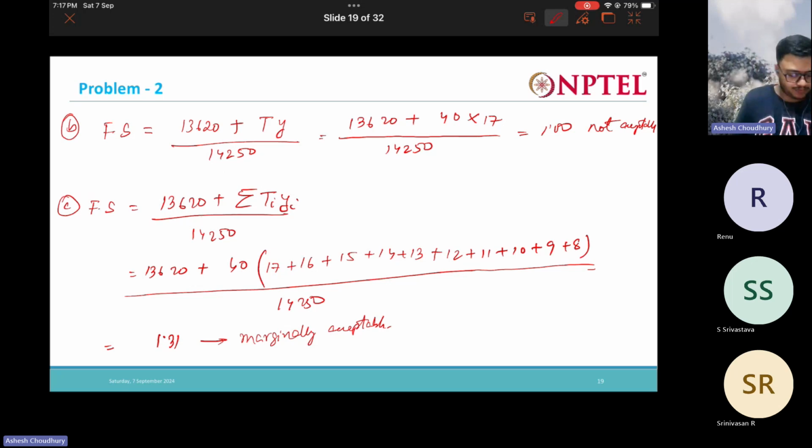All these adjustments you can do in order to increase the factor of safety. Okay. Now we had a fourth part of the question also, right? What if the soil was a frictional soil? In that case, how would we solve this problem? We cannot solve it this way. So we have to consider the wedges.